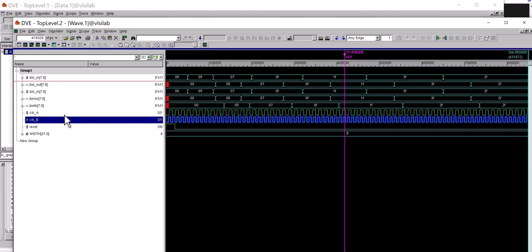Okay, I hope you got the point, but definitely it is not useful for transacting data that has more than 1 bit change. It looks okay in RTL simulation, but while going for the synthesis simulation, I found some glitches at the output side. Even though I placed a proper latch at the output side after the combo of gray to binary, I still saw the glitches.